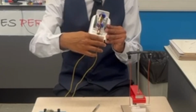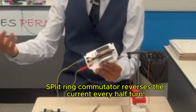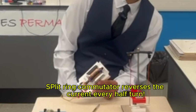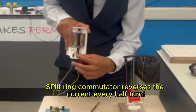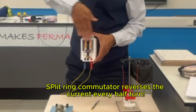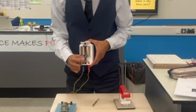Now, we've got a problem. Imagine that the coil is spinning. What's going to happen? The wires are just going to get tangled, aren't they? So what do we need? We need the split ring commutator. So you see that little copper here? Right in the middle here, when the coil is this way, flat, you have got a gap.